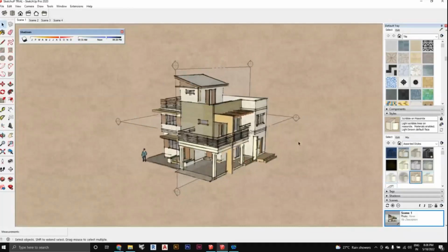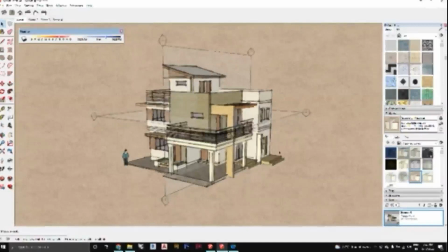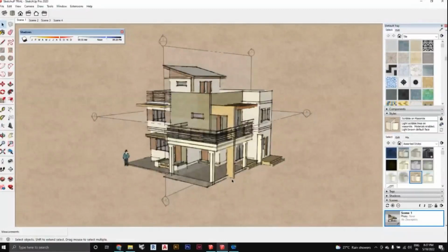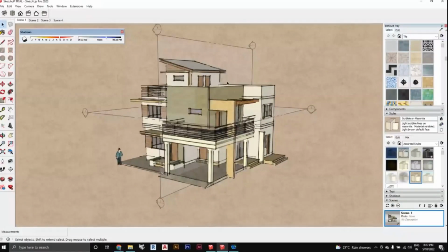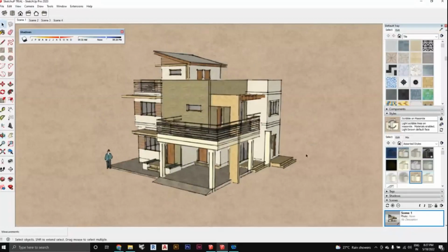You might have seen some of your seniors or some of your people having something like this. Most of you must have thought that this is handmade. Nothing like that, it is basically a SketchUp trick. So they just go to SketchUp and do this stuff. In View, I'm just turning off the section plane so that you can see. So you don't need to watercolor it, or you don't need to make the illustrations, you can simply export this as an image and then put it in your sheet.